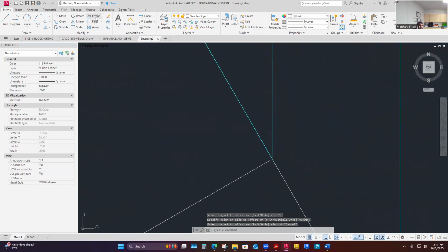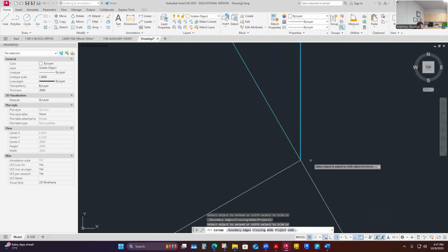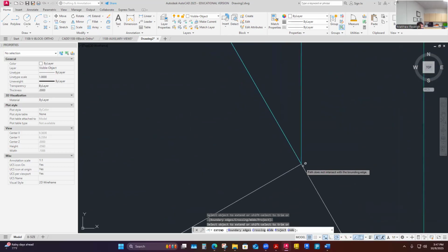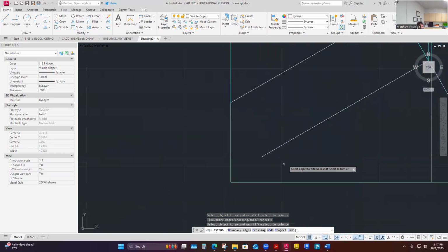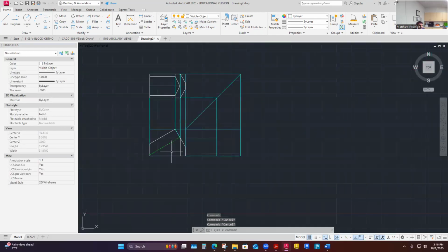Maybe I'm going to extend this here, see if it will. Let me extend that, make sure it lines up with those points. And then I'm going to extend this down here, where it extends through. That's where it would exit. This should be hidden line work, so I might just switch the line type here to hidden.